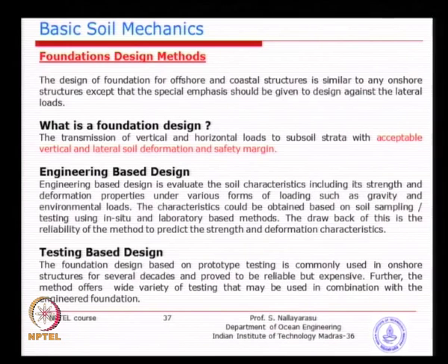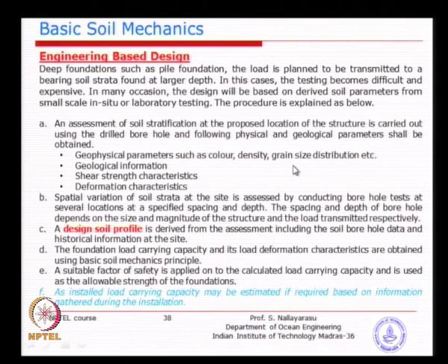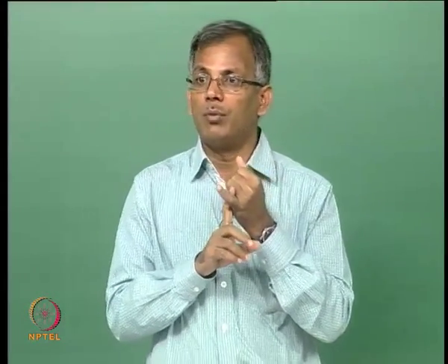So, that is the idea behind foundation design based on engineering. It is a very simple sequential task. The first thing is to establish the soil characteristics. That means the soil stratification at the site has to be established by historical means. You can look at what has happened over several years, or any particular construction activity in recent times in that area, because you will get information with regards to soil boreholes.